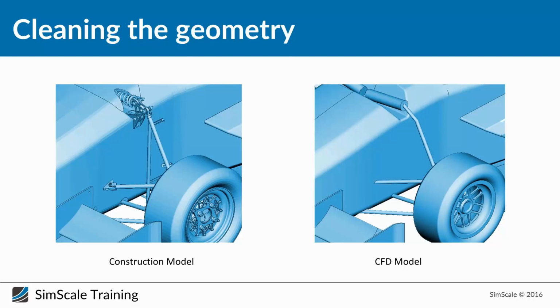Nisha wants to know if we can do surface repairing with SimScale. No, we don't have any surface repairing features, but it's basically not necessary. Honestly, as long as you work with STL files and your model is closed, there should be no need for surface repairing. You should do everything in your CAD system.